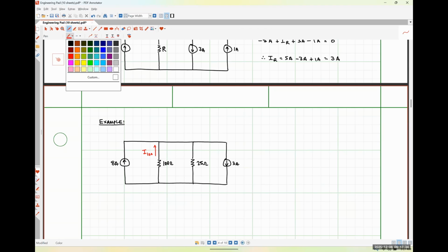Okay, so let me backpedal just a smidge here. So in this particular circuit, where everything is connected in parallel, hopefully we can all see that. This is an example of a single node pair circuit. Okay, so that all of the elements are shared by a single pair of nodes. In this case, the top node and the bottom node. Sometimes you'll see it as everything is between the left node and the right. Okay.